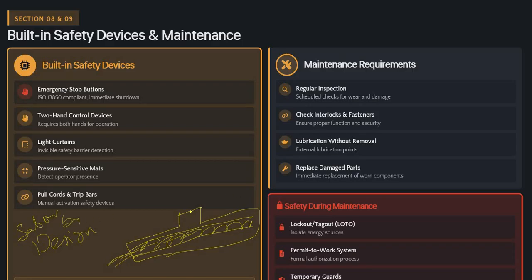There is a chance of the hand getting entangled with this screw press. Now what I will do as a safety professional, when I do the risk assessment, is increase the chute, maybe to 1 meter or something. Now is it possible to place a hand here, to make contact here?